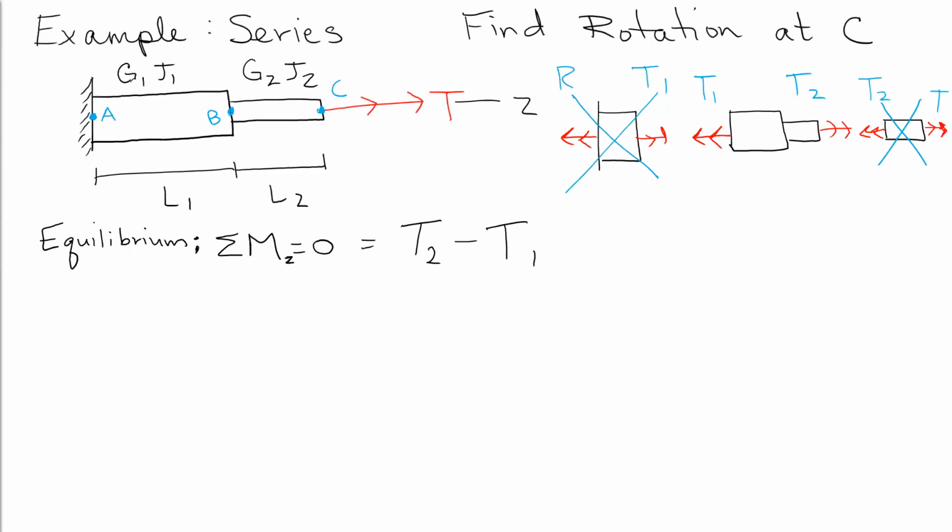So remember, on either side, if your thumb is pointing away, that's positive torque in terms of causing positive torsion in the member. Just like tension is always pointing away, that puts positive normal stress in the member. But equilibrium has an entirely different sign convention.